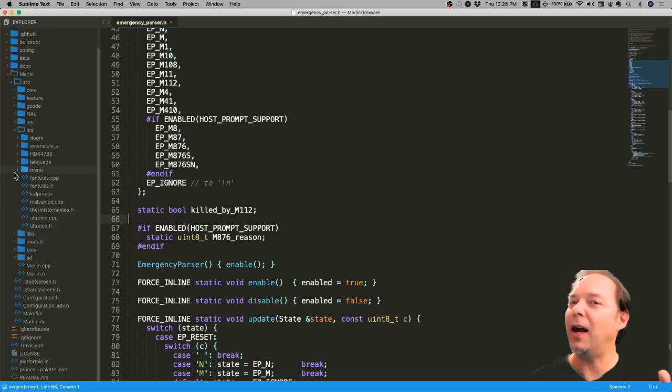So the G-code parser is kind of higher level, just dealing with pulling apart strings and then sending data off to be processed by the low-level stuff. And then we'll look into low-level stuff like the planner, but we'll get into the details. I'm going to continue to take that approach where we start with an overview and then work down to the details, so that you sort of know what to expect, and maybe we don't collide too hard with what's come up ahead.